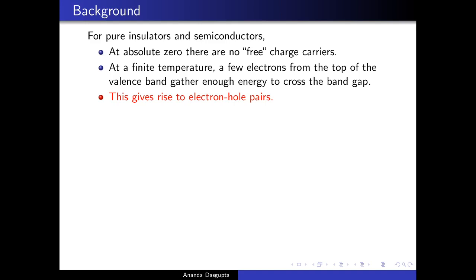What you may not have realized is that you need the electrons whose gaps these are to also have negative mass in order that holes really behave like positive charge, positive mass particles. But that is exactly what electrons behave like near the top of the valency band, and the gaps really behave like positive charge, positive mass particles, which we call holes.